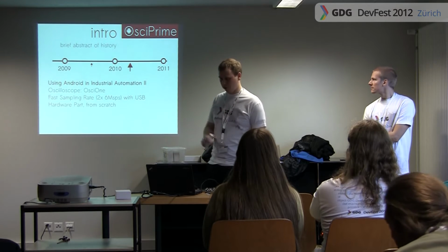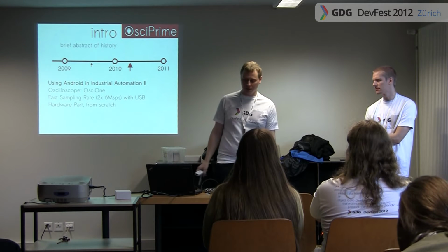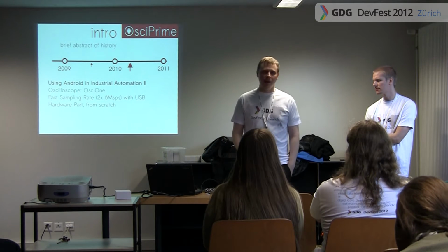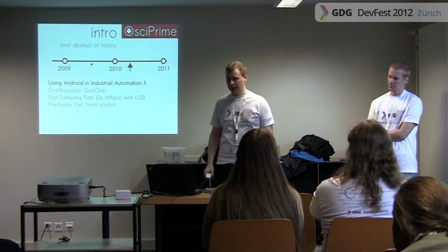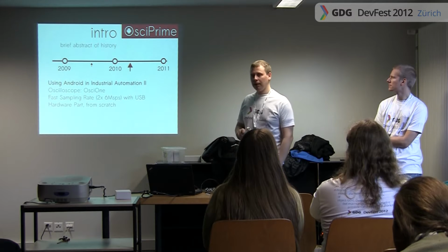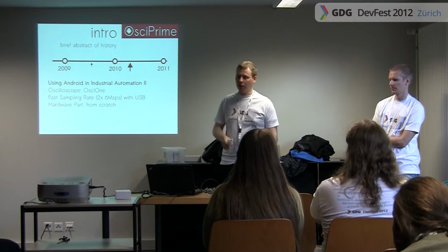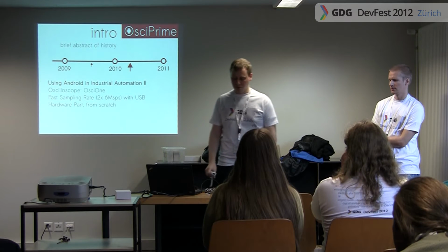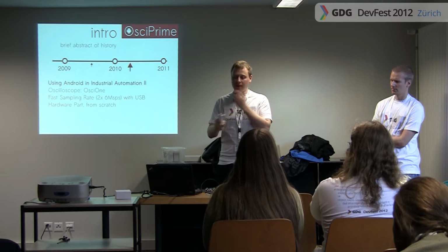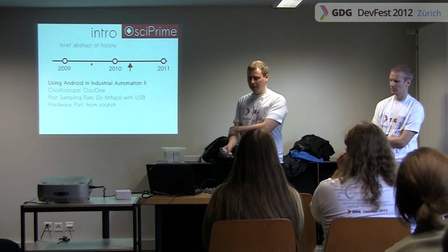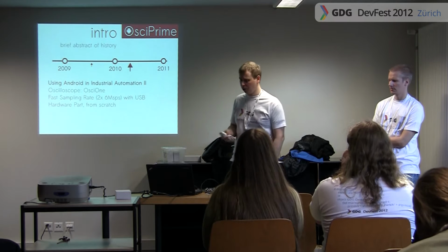And what we used was, for continuous transfers, 6 megasamples per second with 2 channels on the oscilloscope, and that is not at the limit of USB, however, it ensures that you won't lose samples. And when you see here 6 megasamples for an oscilloscope, that might be pretty low if you compare it with purchasable big oscilloscopes, like you find them in the market. However, keep in mind this is transient, so you can record the data, and it is not like only snippets of the data. So that was really cool. You could use it as a logger.